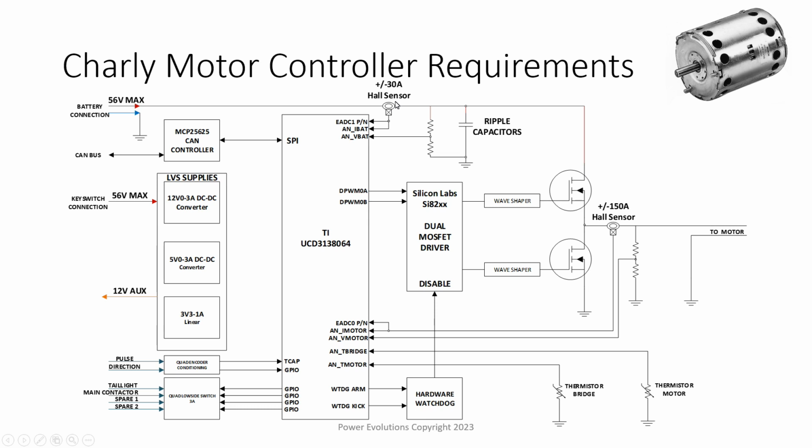This is a plus or minus 30 amp sensor, so a little bit better resolution, not hugely. 2 amps is still limited, but since the battery is limited to 25 amps output, this will fall in quite nicely in the range.